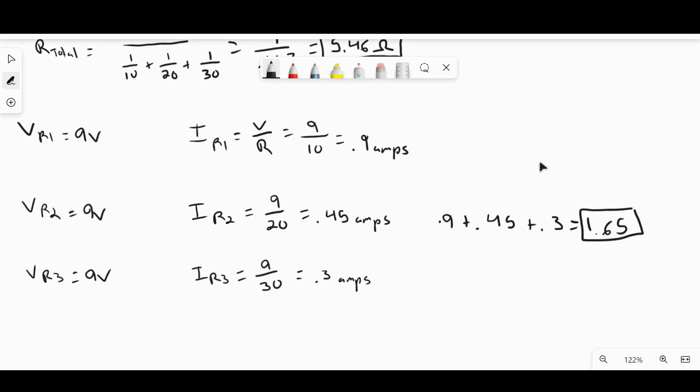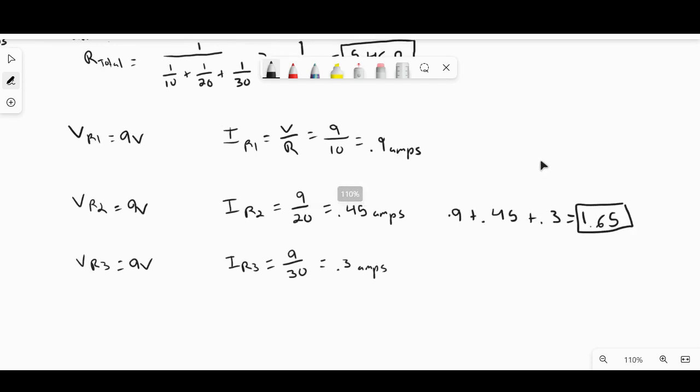All right. So using Ohm's law, why do we need this? Why do I need to know about voltage and current going across different loads? Well, one of the most basic examples is if you have LEDs in a circuit. LEDs have a maximum amperage operating value. If the amperage is too high, it will actually blow the LED, and we don't want to do that. So depending on the power supply you have and the specifications of the LED, you'll need to use Ohm's law to figure out maybe what resistance you need with that LED so it illuminates but doesn't blow out.